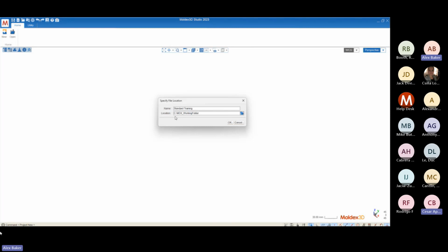That communication can be delayed if there's a network connection or any sort of external connection, and at the best case scenario, it will cause your simulations to bog down and your computation time will be longer than necessary. In the worst case scenario, and especially in the case of a network drive, that connection can be broken, in which case the connection to the solvers is broken and the simulation terminates and you waste a bunch of time.